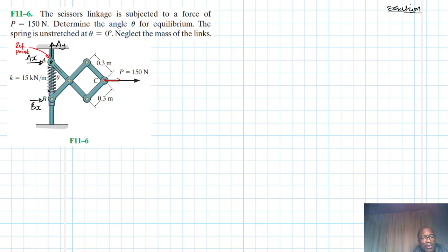But is it okay if I applied it in the opposite direction? Of course, it's okay. Nothing gets disturbed because the configuration and the displacements won't really get affected. The constraints are still there, and when you work on the algebraic sum of the total work in the system, the answer will still remain the same.